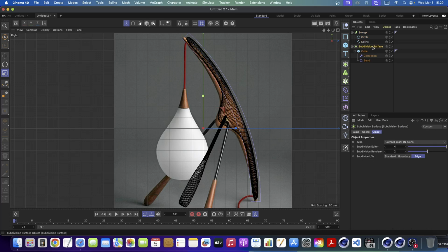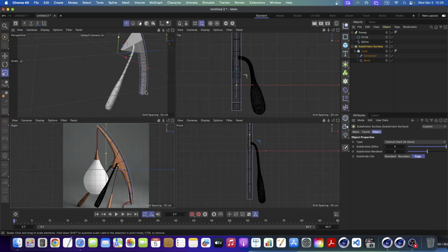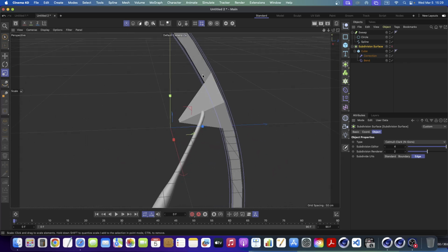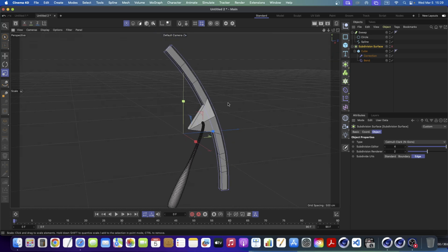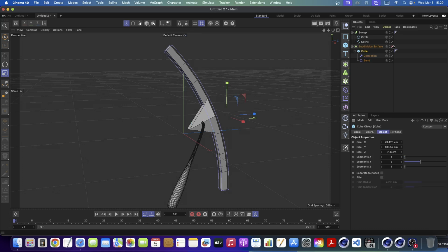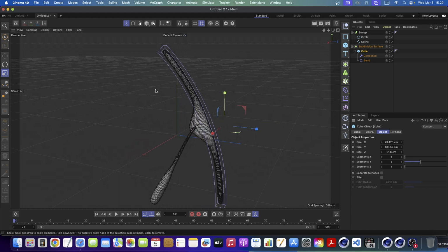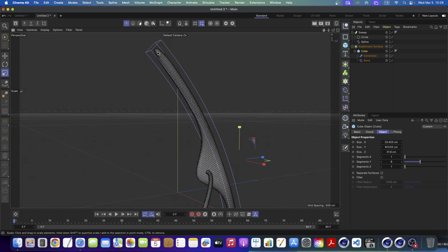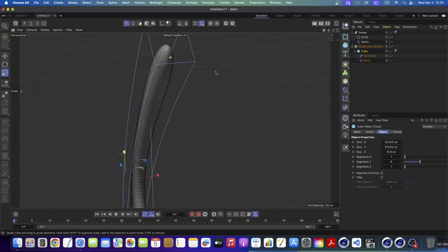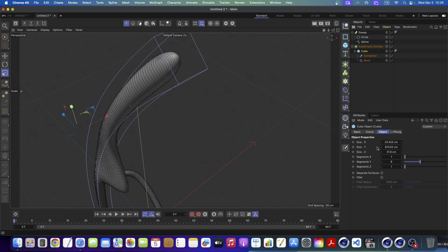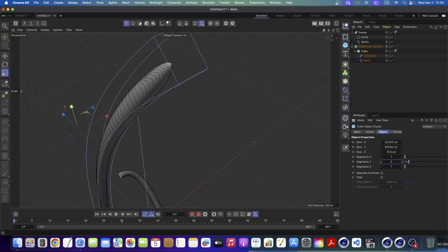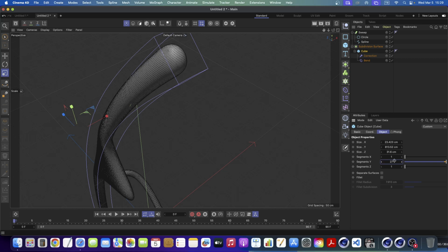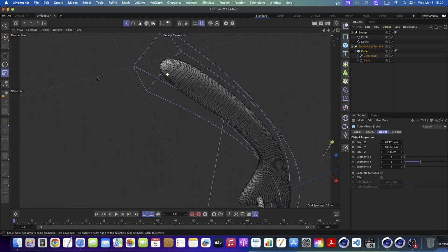I've put that inside a subdivision surface. So normally it was something like this. The cube was something like this. And let me. So there are not so much subdivisions, not so much segments in this cube. If I put that into subdivision surface, and when it smoothens things up like that, it crushes down those edges to something similar to this. Okay, but if I increase the segments of the cube, it will be something like this. Look at this. It won't be so thin. So because of that, I don't want to increase this too much. So it was 8, segments was 8.